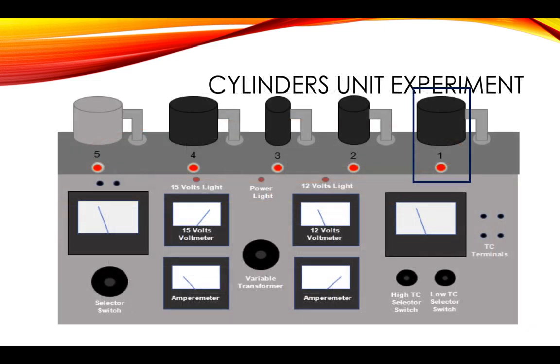In this experiment, the selector switch in the control panel was adjusted to 1, turning on the light in cylinder 1. Then the high TC switch and the low TC switch were also changed to 1. The transformer was set to 12 volts so that the ammeter would provide 6.5 amps. The internal temperature for cylinder 1 was monitored until steady-state conditions were reached, with the aid of a pyrometer and a thermocouple attached to its corresponding terminal.